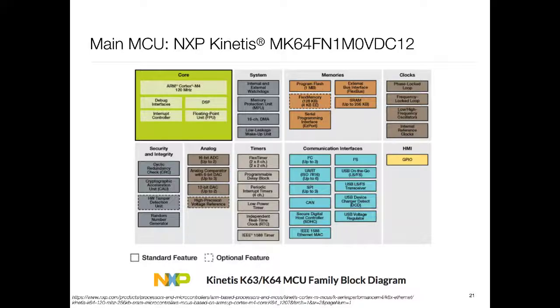Then on-chip memory, clocks, a whole bunch of timers, analog interfaces. In this case, it has ADCs. It's a bit hard to read, but it has ADCs and DACs both, so it can take in and emit analog signals. It has support for security, so in particular, it has a cryptographic unit, so it can accelerate certain crypto functions. It has a random number generator. Random number generators are used by a lot of security protocols as part of the key mechanisms, and then a whole bunch of communication interfaces.